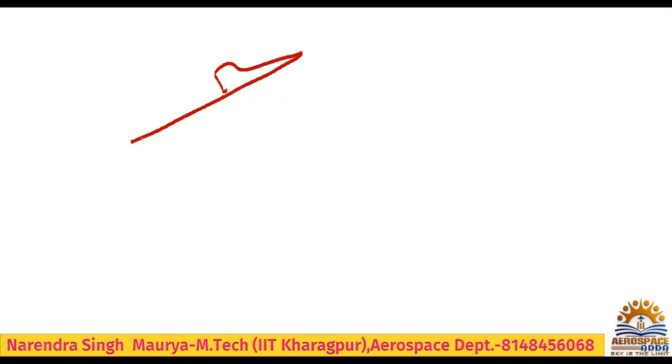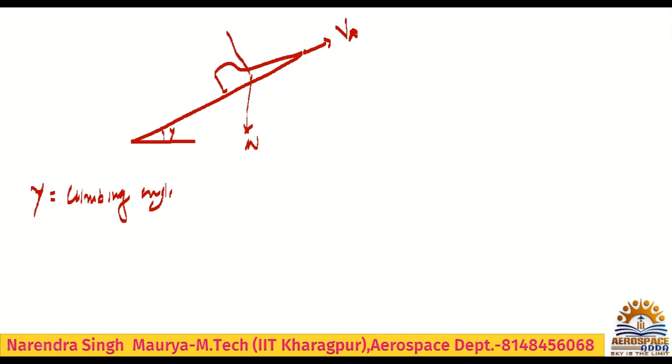This is the aircraft which is climbing with climbing angle gamma. What is gamma? Gamma is nothing but the climbing angle with V infinity. W is perpendicular to V infinity. We have lift force, and this angle will also be gamma.